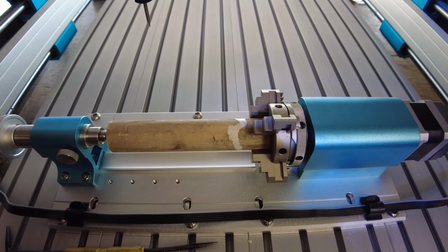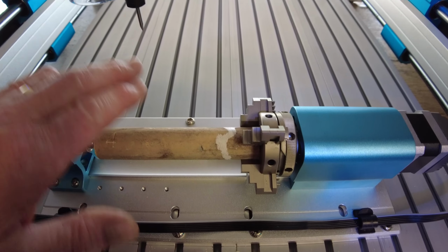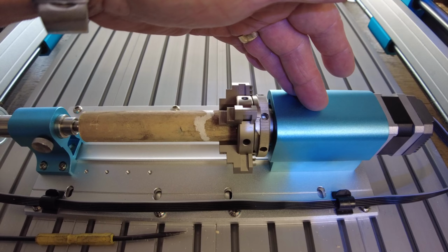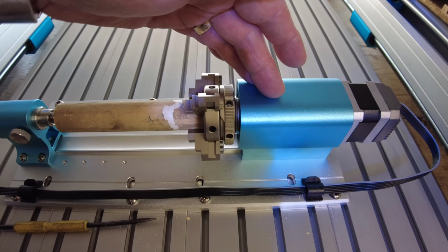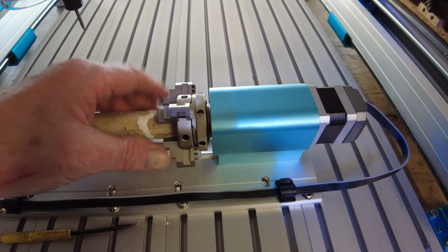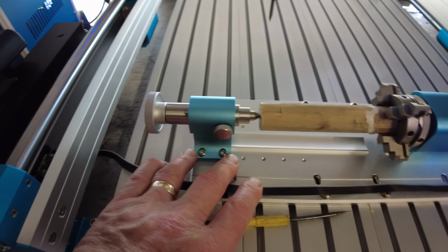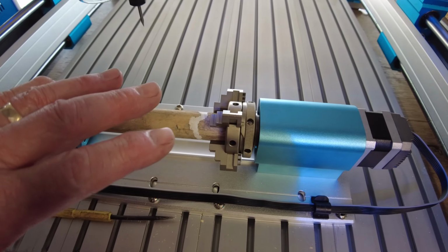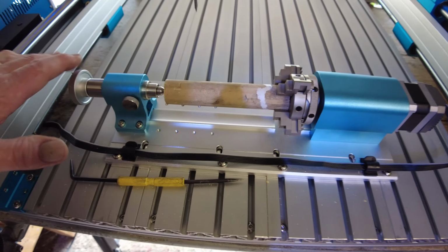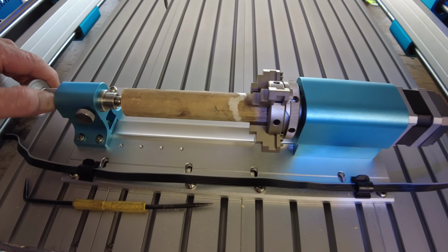You could probably get slightly bigger diameter as well if you take this off of the plate, the chuck, and mount it on a higher one, and just use the chuck. Or you could match the tailstock up as well and lift it up to give you some more diameter. But there again, you're going into the realms of spending a bit more time and probably a little bit more money.